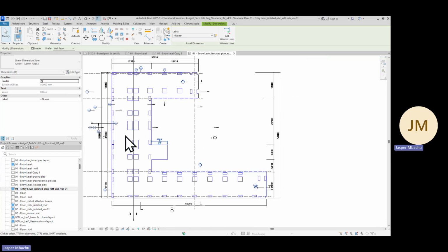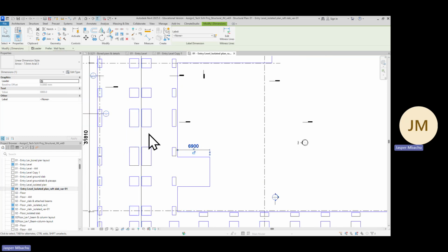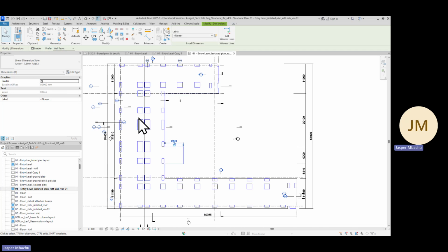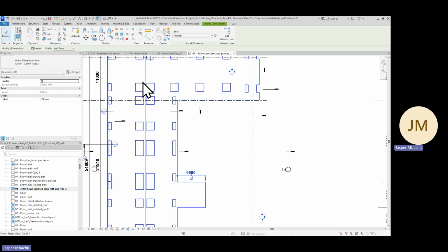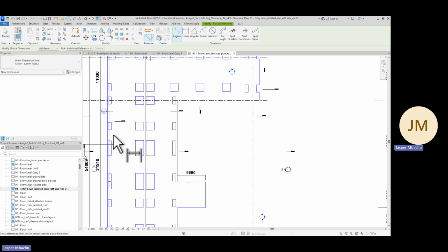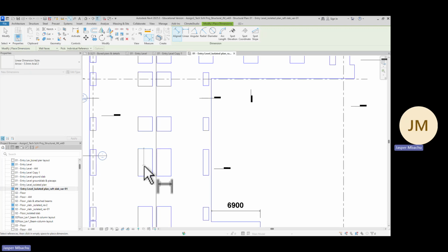And if I want to show this other dimension, which I should have shown, because the one that I provided on our line set has this dimension, we want just to have an instance of 3 instances. One is a dimension of 2000 by 2000, a dimension of 1800 by 800, and a dimension of this other long one. So I just use annotate, aligned, and get this dimension. Okay, this is 3840. Yours might be different.